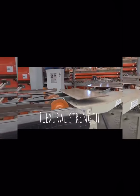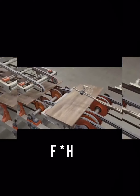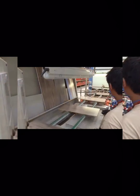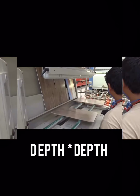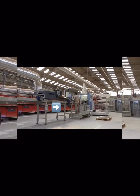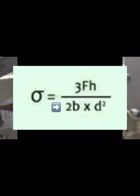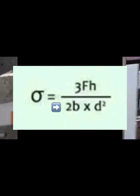So to calculate the flexural strength, multiply the force by the length of the sample and then multiply this by 3. Then multiply the depth of the sample by itself, or just square it. Multiply the result by the width of the sample and then multiply this by 2. Finally, divide the first result by the second.